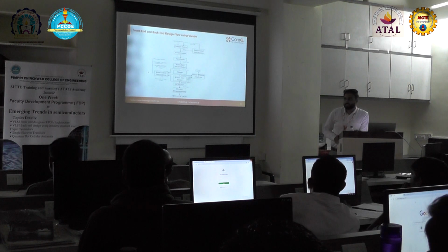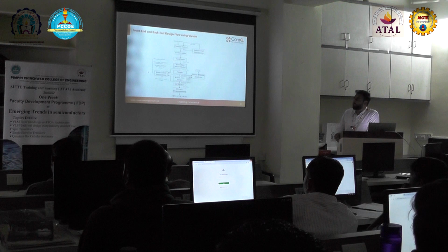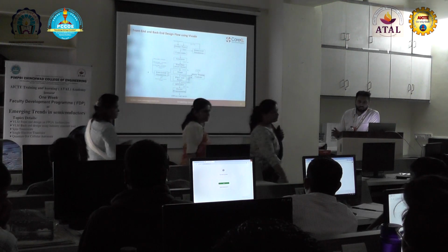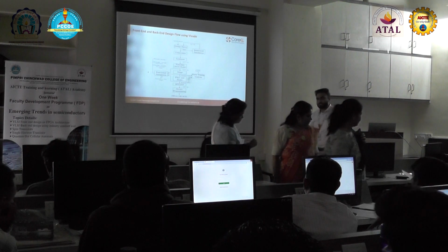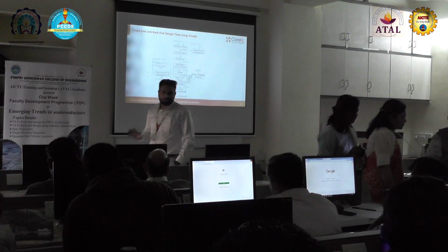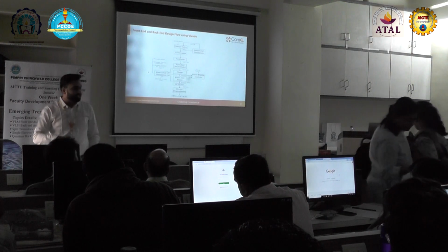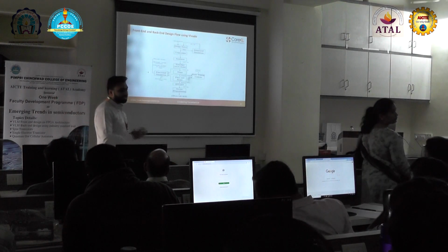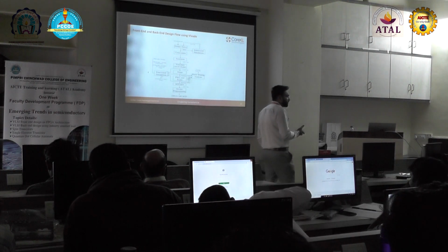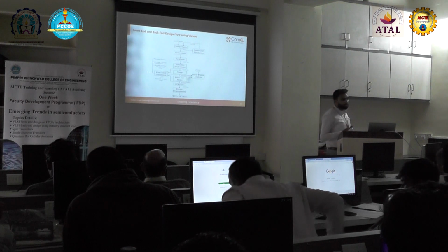So in the synthesis stage, we will have the estimation of the input-output utilization. Only the estimation, that is not the final one. We will get the estimation of the reports. But once the implementation has been done, we will get the exact utilized resources and the reports of timings and the reports of the cost.